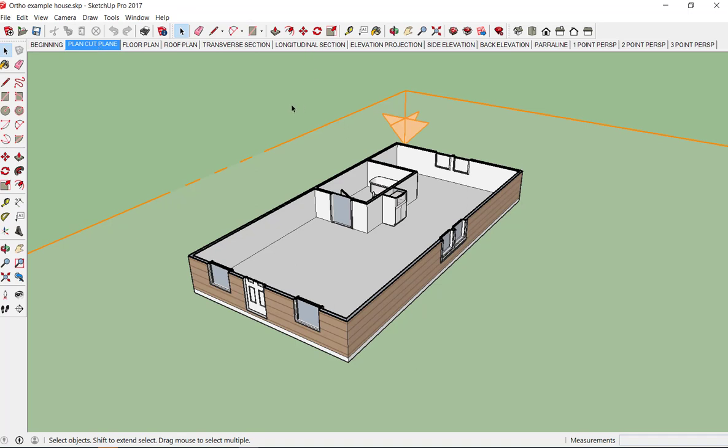That's your cut plane. Now for the actual floor plan we don't draw it in 3D view like this, because you cannot. If I printed this out on a piece of paper and I took my ruler and scaled this and scaled that, it would scale at two totally different dimensions because it's not to scale. This back one is foreshortened because of the perspective effect. So when we make a floor plan, we look straight on it.